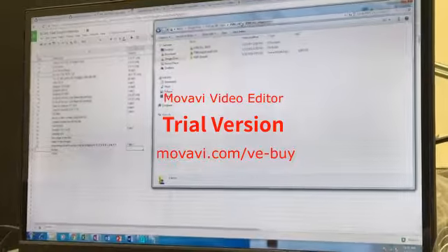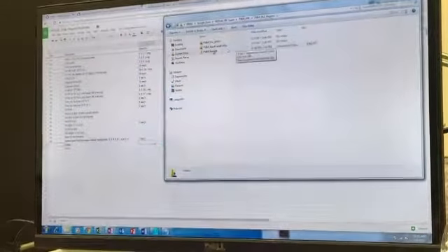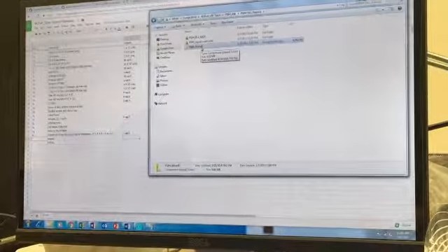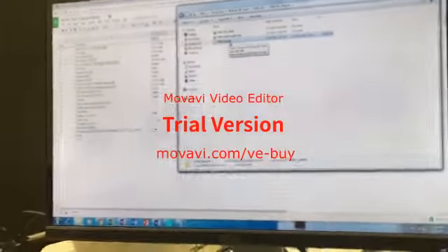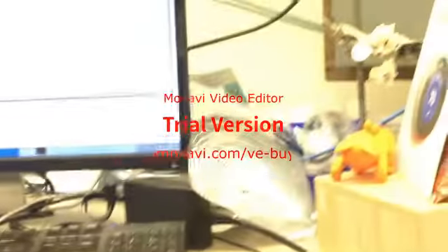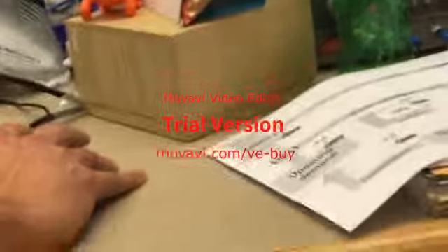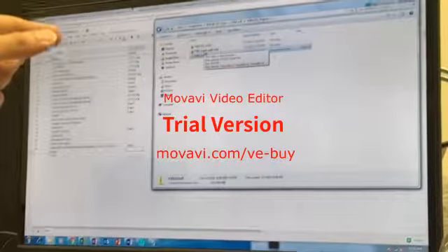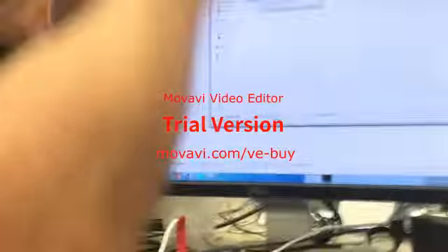So in the PSIM DLL projects folder, there is a base DLL zip file. Use the zip file when you want to make your new DLL block. Anytime you need to make a new one, use the zip file and unzip it and then reconfigure it from there. Because for some reason, if you take the folder and you copy it, and then you use that one, what happens is that the different files become linked to each other.